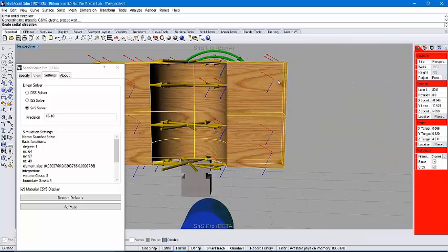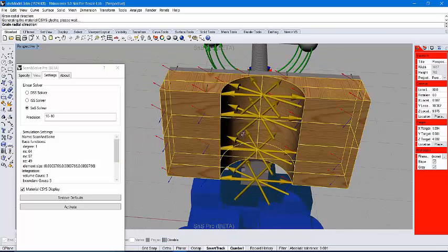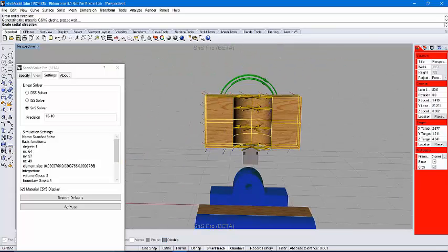You also have to use it if, let's say, your material is a cube or has two sides that are equal length. Scan&Solve can't assign the radial or tangential grain direction if it doesn't have one side longer than the other. So you'll have to use the Specify tab for those situations.